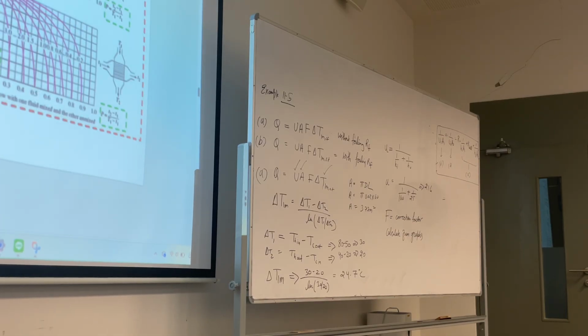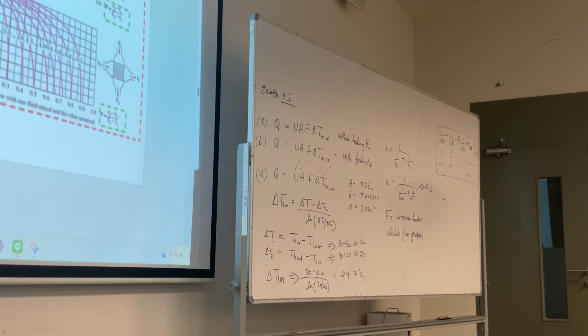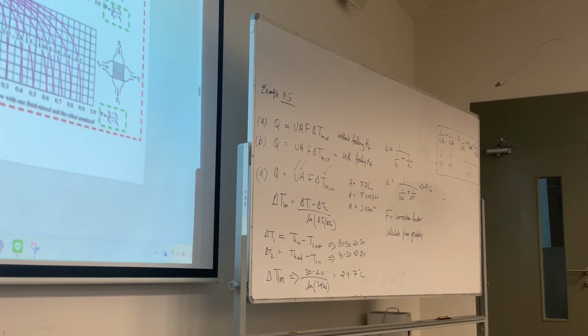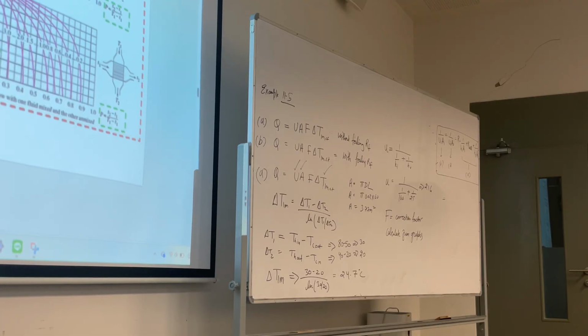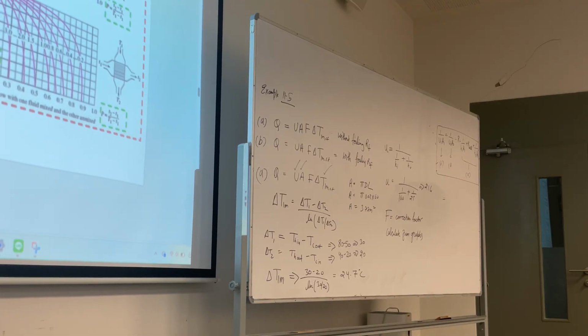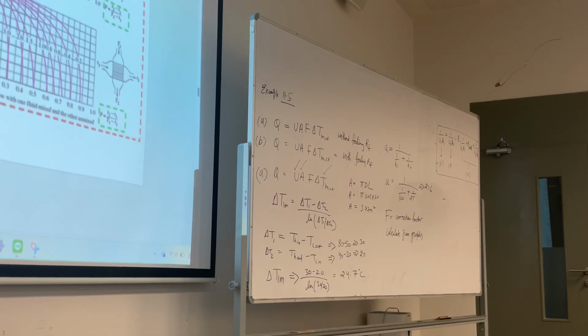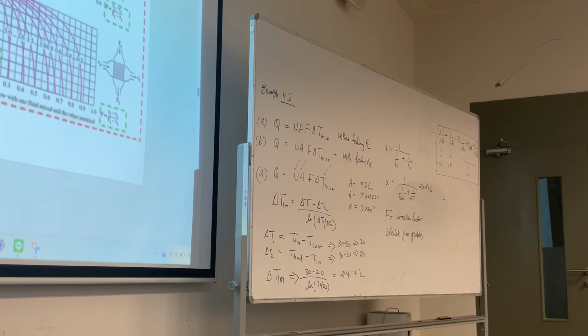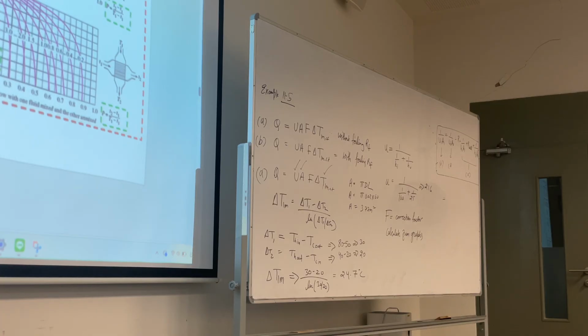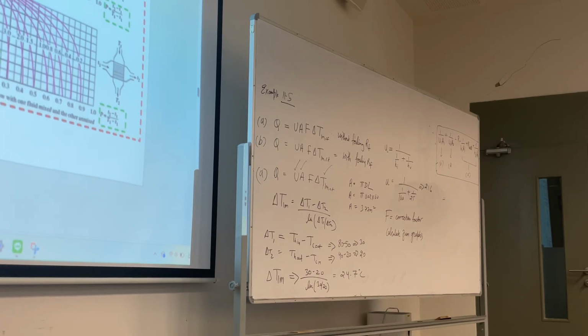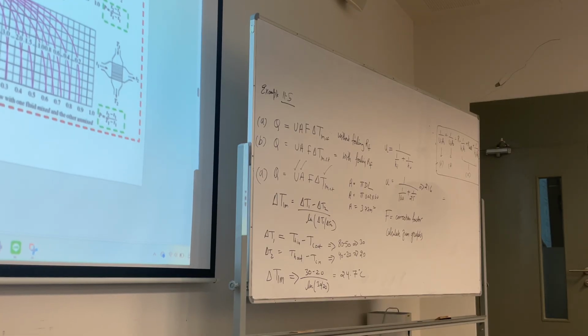So this graph, we will look at this graph and we have to calculate F, correction factor. So we need to calculate x-axis and these pink lines, and similarly like we did in chapter 4, if you remember Heisler chart. So in Heisler chart as well we were using the graphs, right? So similarly calculate the x-axis, calculate the pink line, and then track to y-axis, and y-axis is the correction factor.